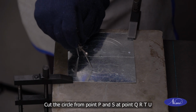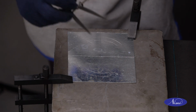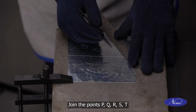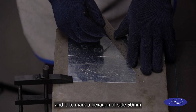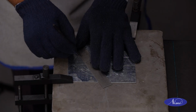Cut the circle from points P and S at point Q, R, T, U. Join the points P, Q, R, S, T and U to mark a hexagon of side 50 mm using a steel rule and scriber.